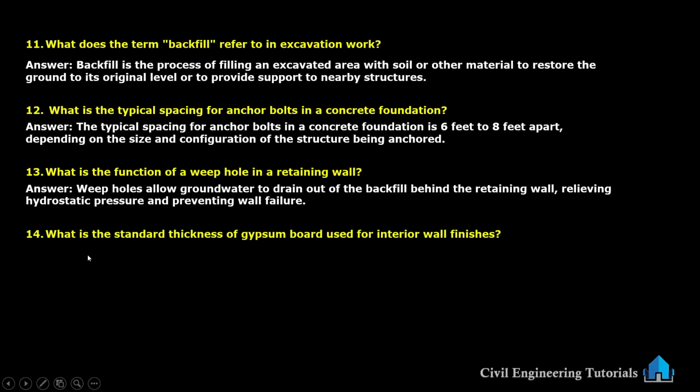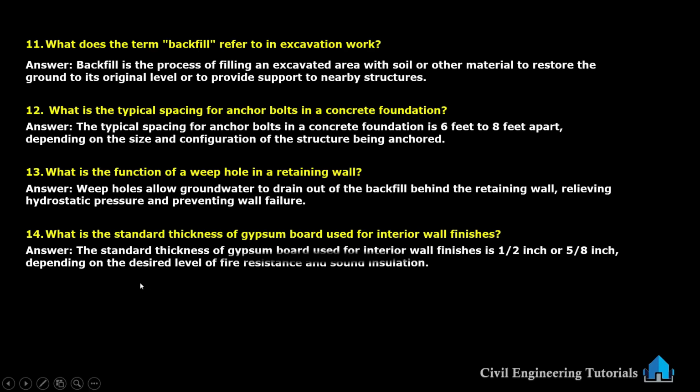What is the standard thickness of gypsum board used for interior wall finishes? The standard thickness of gypsum board used for interior wall finishes is half inch or 5/8 inch, depending on the desired level of fire resistance and sound insulation.